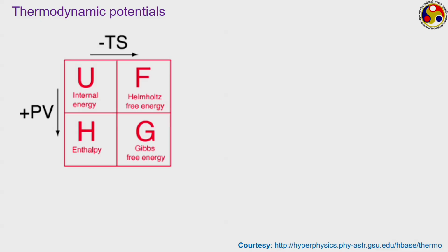Then what is enthalpy? We know to get enthalpy we have to add this PV with U. Here all symbols are shown in extensive sense; if we write in intensive sense, then we know that h is equal to u plus P into specific volume. So, with internal energy we have to add this flow work, and this flow work can be visualized as the work you need to make some space for this particular system. So, enthalpy is representative of the amount of energy needed to create the system plus the amount of energy required to make some space for the system. This is enthalpy. Then what about this capital F?